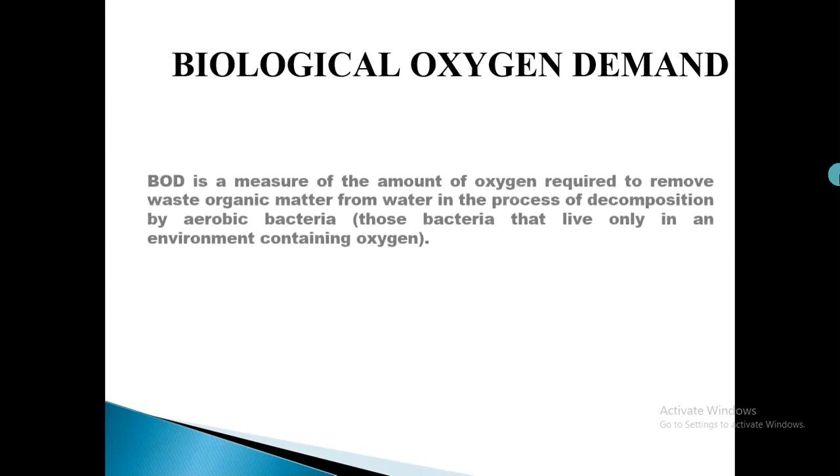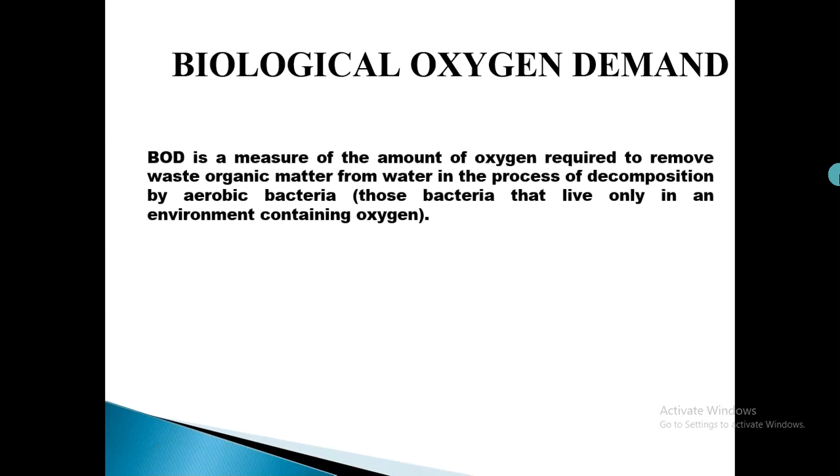So what is biological oxygen demand, BOD? Biological oxygen demand is the measure of the amount of oxygen required to remove waste organic matter from water. Whenever you are removing organic waste matter, which is the human dirt, from water, it happens in the process of decomposition by aerobic bacteria, since the aerobic bacteria consume that human wastewater.